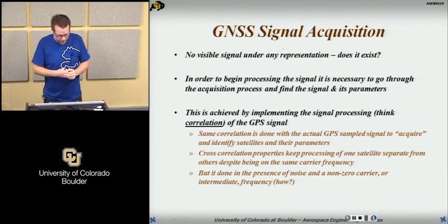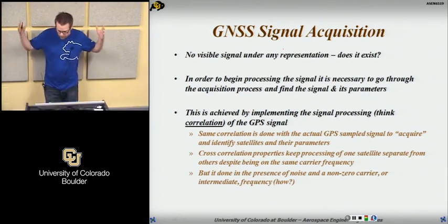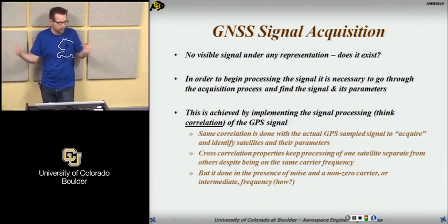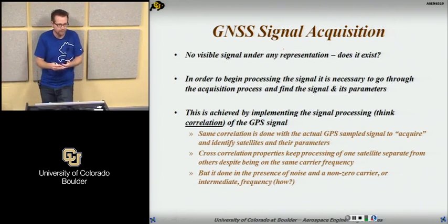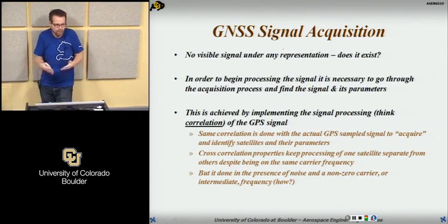What we looked at last week was a 1023 chips long code, and its autocorrelation. We saw there was a strong peak, right? We saw that the codes didn't correlate well with each other, meaning that we only got noise if we correlated the signal from PRN1, satellite 1, with PRN2. That goes for all the other combinations, but I can't be bothered to show you all.